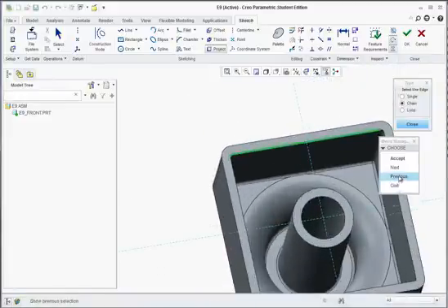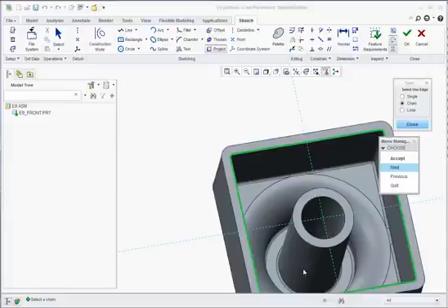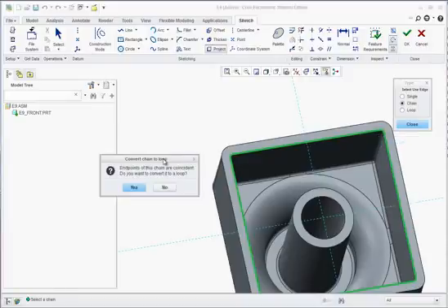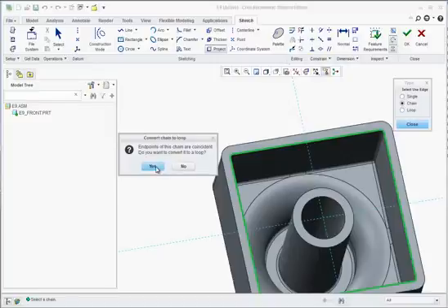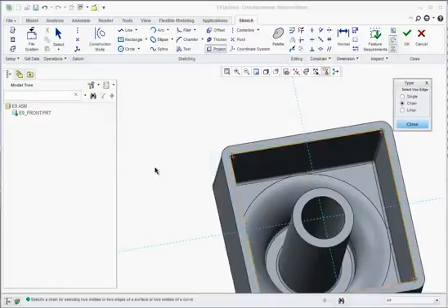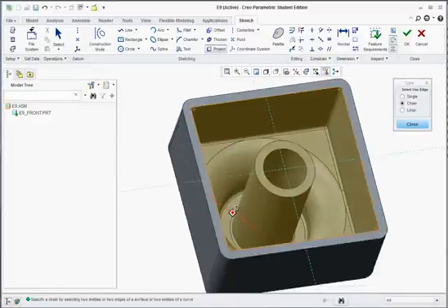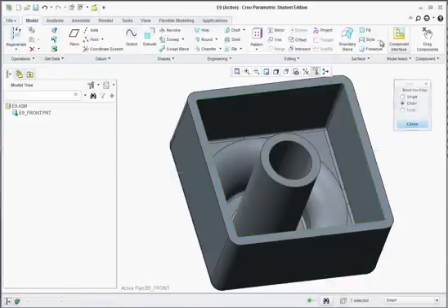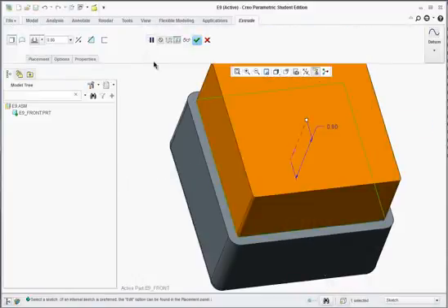and then it's going to allow you to hit accept when you see the edges highlight. Unfortunately, the highlighted edges don't always work very well, but I'm going to hit next. There we go. We could actually see it highlighted all the inner edges. It doesn't always work, but looks on this new version seems to be working pretty well. Hit accept, and it'll tell you, do you want to convert it to a loop? Just hit yes. Okay, at this point, we could hit OK, and we could go to extrude.